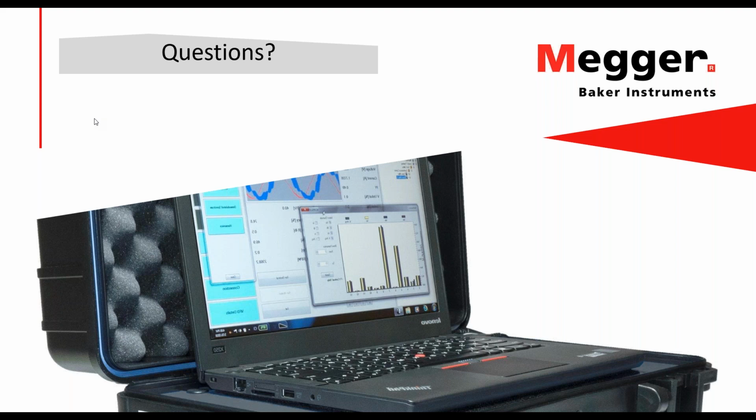We actually use that nameplate information to estimate speed. We use that nameplate information to estimate the torque and derive torque from the voltages and currents. Now, other things that help us become more accurate at the information we're giving you would be lead resistance.